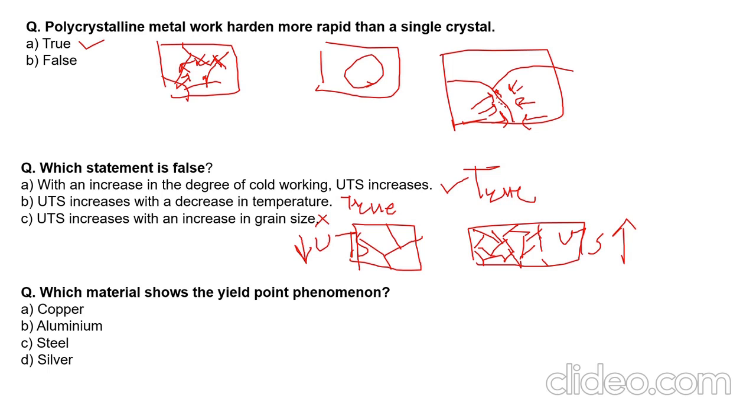No, that is right, because there is a certain temperature where the material undergoes ductile to brittle transformation. But those are very low temperatures. We are talking about normal room temperature and some above, ambient temperatures, not the very low temperatures at which the transformations take place, right?